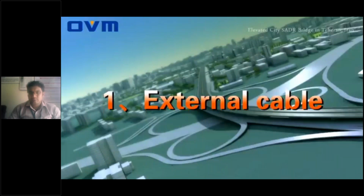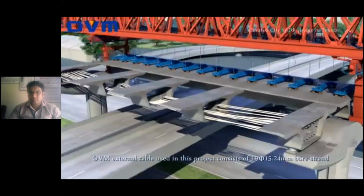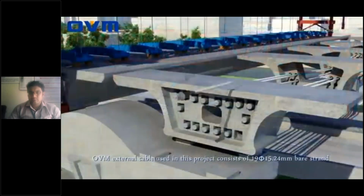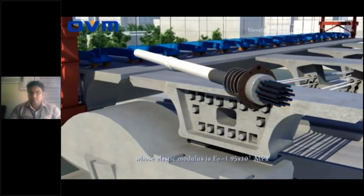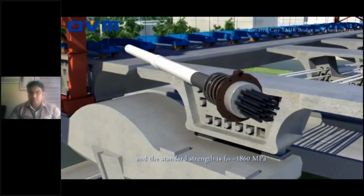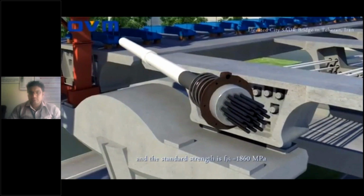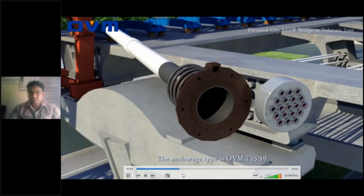External cable. The OEM external cable used in this project consists of 19 by 15.24 millimeter bare strand, whose elastic modulus is Ep 1.95 by 10^5 megapascal, and the standard strength is fpk equals 1860 megapascal. The Anchorage type is OVM.T15-19.